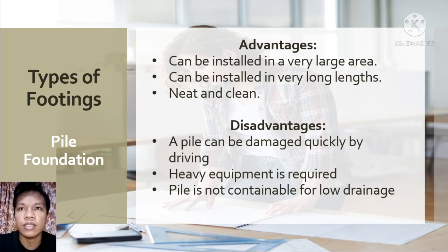And disadvantages: a pile can be damaged quickly by driving through stones and boulders. Vibration is generated when piles are driven, which affects the neighboring structure. Heavy equipment is required for driving the piles. Pile is not suitable for low drainage.